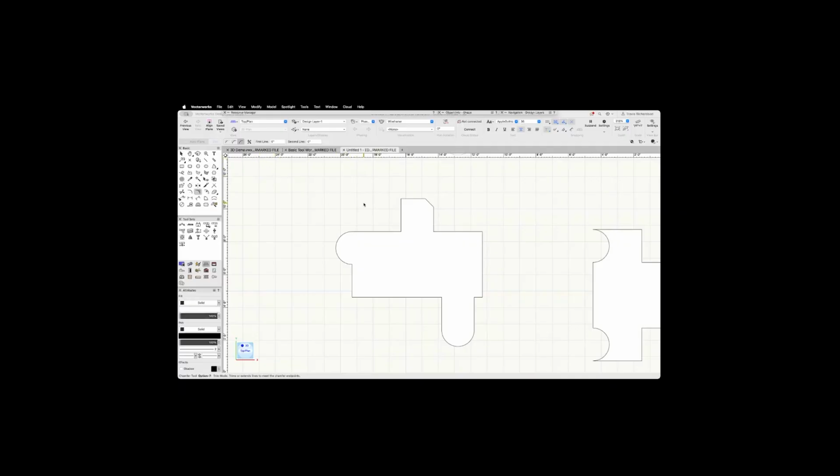and I've made it more of an angled 45-degree corner with that chamfer. So now I'm just going to go along like I did with the fillet tool, and chamfer each of my 90-degree intersections so that all of them have a chamfer to them, and my new polygon will look just like that. When I'm all done, again, I can hit X to activate my selection tool. I can click an empty space just to deselect anything I may have had selected, and I'm all finished.